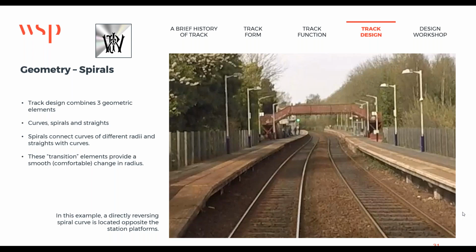And if you think about it, if you've got elements that don't meet the 2-second rule in your design, you've got lots of fussy design. And as a track designer, you're trying to achieve the longest elements that you could possibly give so that you have a simple track alignment. Simple track alignments run good, are easy to maintain, and you will keep them forever because they are simple.